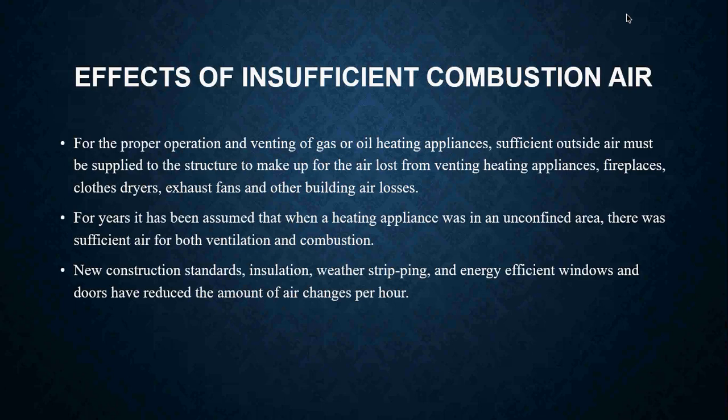For proper operation of any gas or oil heating appliance, you've got to have sufficient outside air supplied to the structure to make up for the air lost from venting appliances, such as your fireplaces, clothes dryers, exhaust fans, and other areas of the building that are losing air.